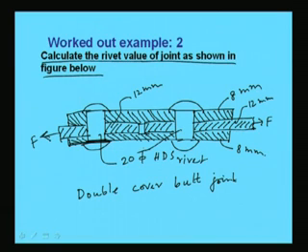So, this is the detail of the joint, that is the rivet is used as 20 mm hand driven shop rivet, and the extra plate which has been made, that cover is 8 mm and the thickness of the main plate is 12 mm. So, here what we will calculate?